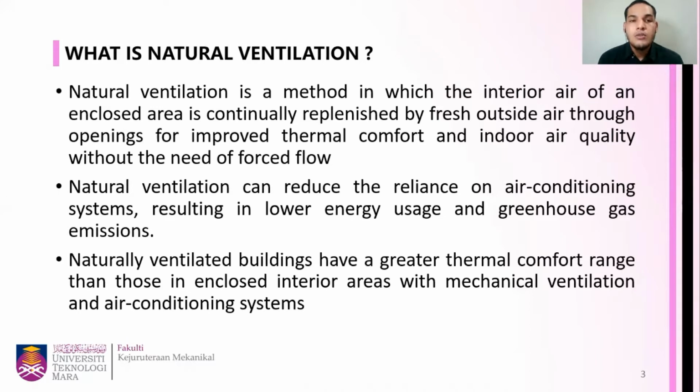Next, we will go to natural ventilation. What is natural ventilation? Natural ventilation is a method in which the interior air of an enclosed area is continually replenished by fresh outside air through openings for improved thermal comfort and indoor air quality without the need of forced flow. Natural ventilation can reduce the reliance on air conditioning systems, resulting in lower energy usage and greenhouse gas emissions. And lastly, naturally ventilated buildings have a greater thermal comfort range than those in enclosed interior areas with mechanical ventilation and air conditioning systems.